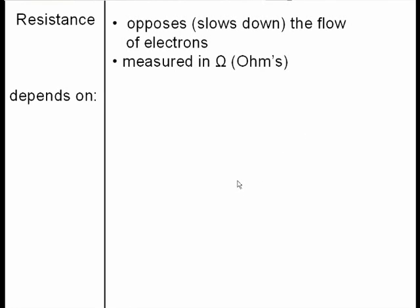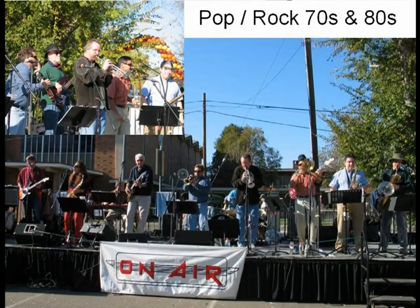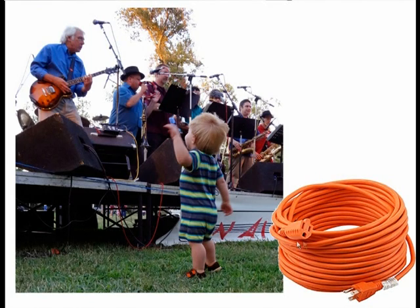So this resistance depends on several things. One of them is the length of the wire. So this is the issue I have with the bands that I play in. I played in a salsa band for 15 years, and I played in a rock band for 33 years now. And one of the issues we have is when we're playing on a stage that's out away from electrical outlets, this one's out in the middle of a park, the people who hire us give us this big extension cord thinking we're going to run it all the way to the end of the park and plug it into a wall somewhere. Well, the longer this cord gets, the less and less power we can get through the cord, and we have all kinds of problems running our equipment.